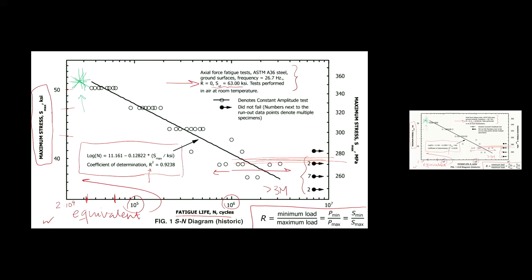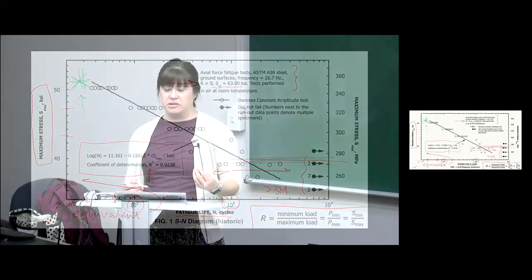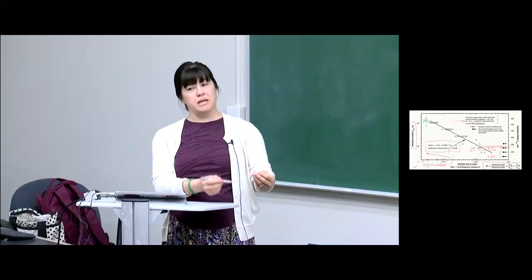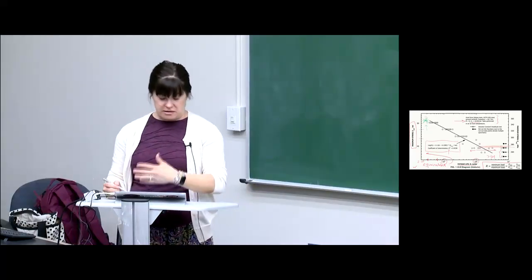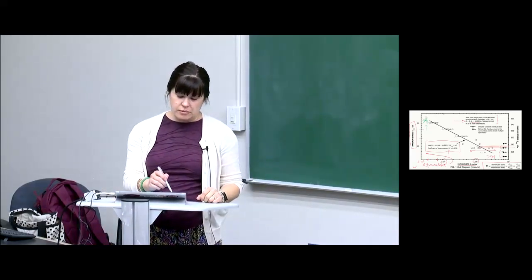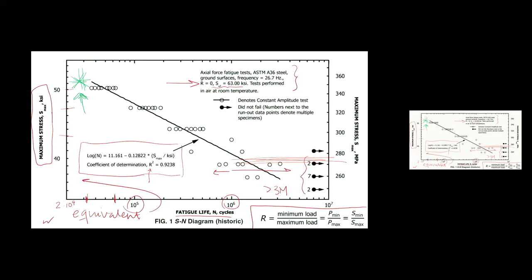design for low cycle fatigue, right? So applications where there would be less than 1,000 operational cycles, applications that are very specific or that experience extreme conditions, right? So pressure vessels that hold nuclear material or something like this, right? We don't have magical materials that we just mine out of the earth and use for those applications. We have to use the best materials that we have available. And so we also have to understand how those materials operate in low cycle fatigue conditions.